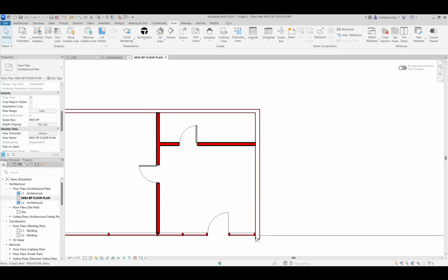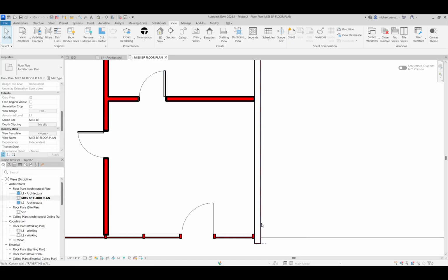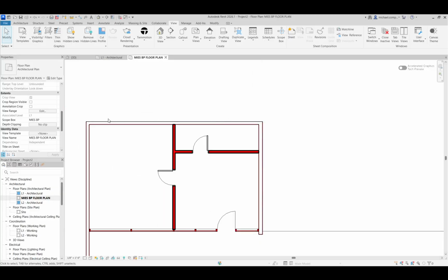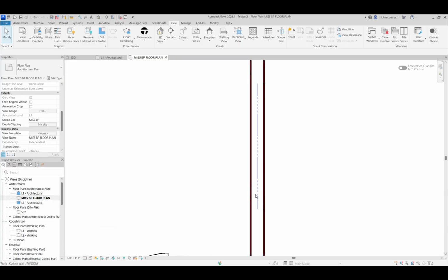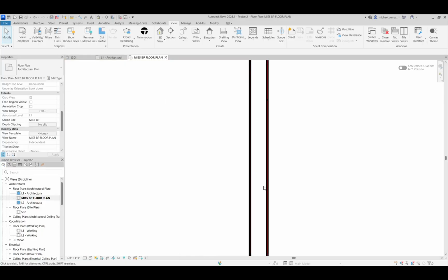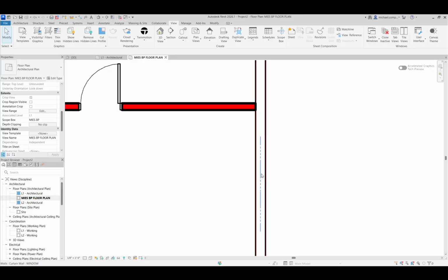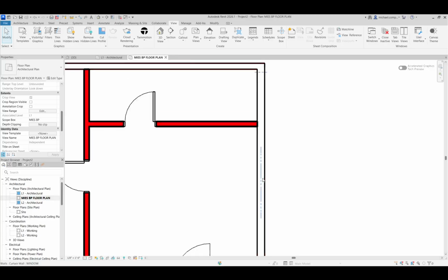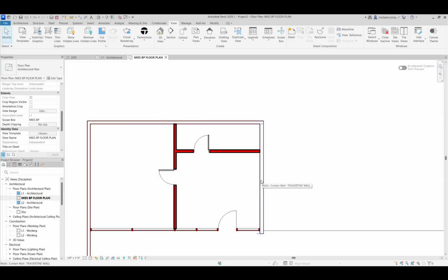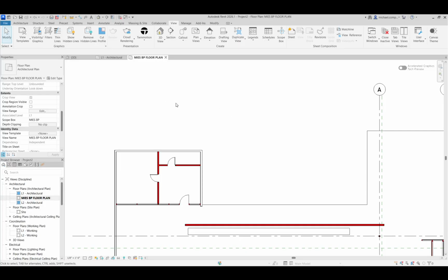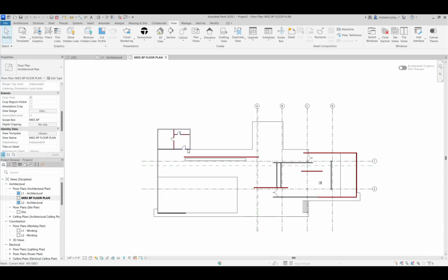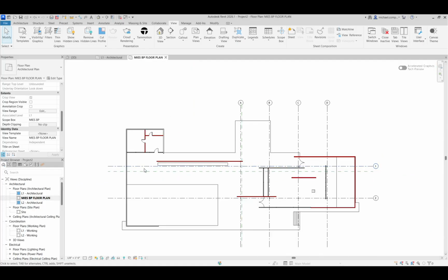What I don't have shown are the structural tube columns marching down the interior, but what is shown is the travertine marble panels, and those things are being cut through. So there's actually a gap, an air gap there. That's why you're not seeing anything there. And it's also the way we constructed it using freeform mass. So that's okay. It's not a mistake that those aren't highlighted red and everything else is, or everything that's being cut is. Reminder for those who aren't familiar, floor plans are truthfully sections. They're horizontal sections instead of vertical sections.